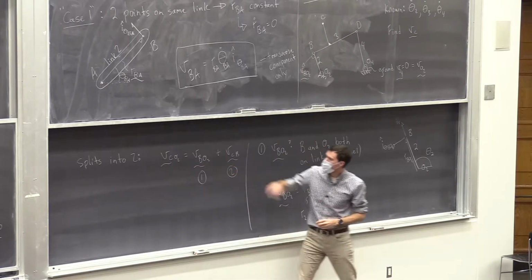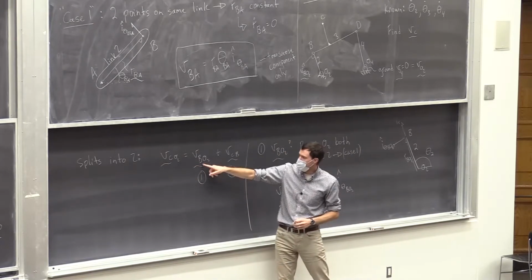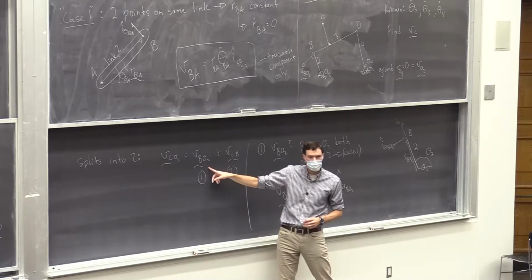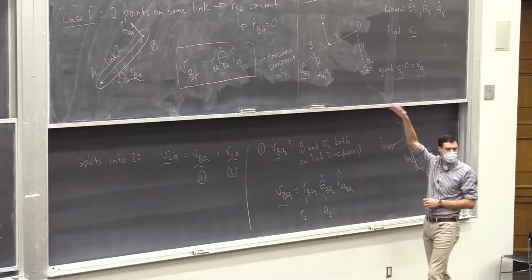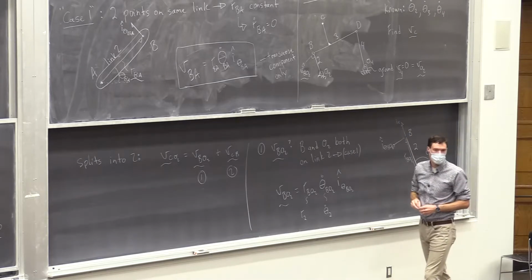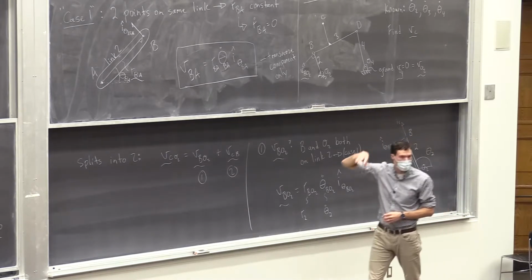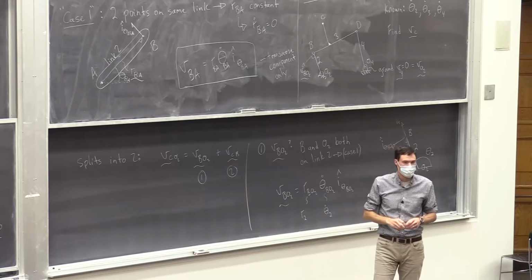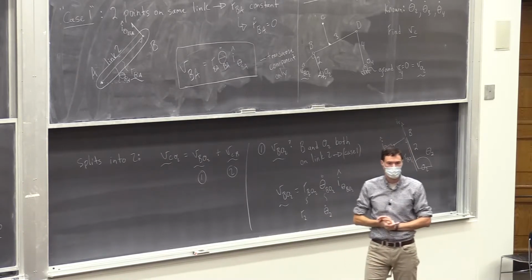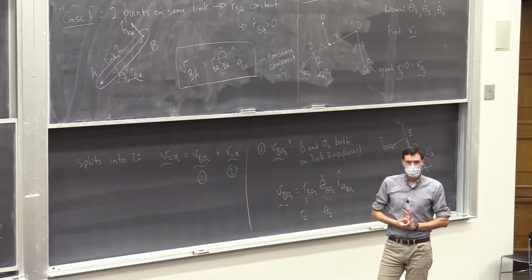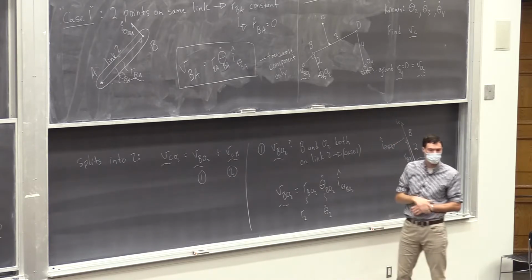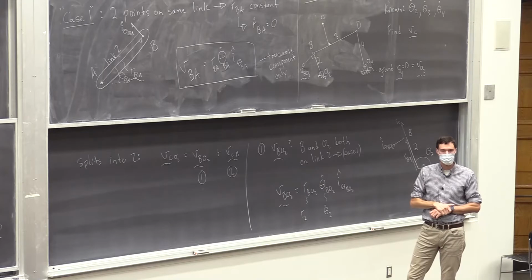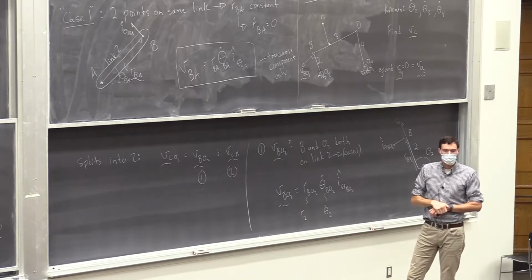You would have done velocity of D relative to O4 plus velocity of C relative to D. That would be an alternate solution method, stepping through point D instead of B. And you could check your work that way. Right now we're just looking at O2 and C because that's what the question asked for, just to find BC. But what if there were more turning points in between those 2 points?